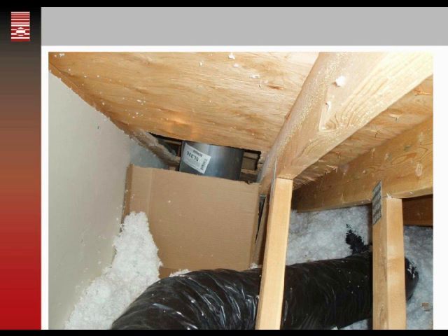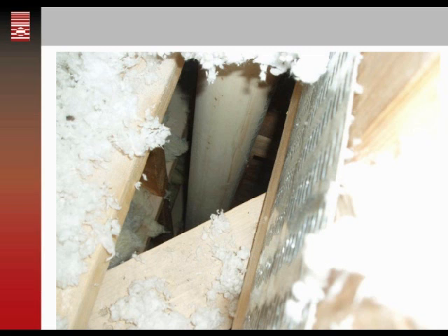And then we're looking at a fireplace chimney, and that fireplace is actually down in the basement, and when we pull back that cardboard ice dam, you could see all the way down to the basement floor. So another large bypass coming up and bringing heated air up into the attic.